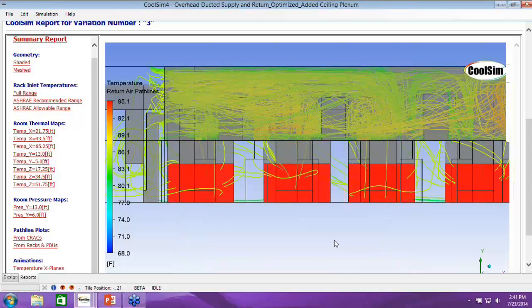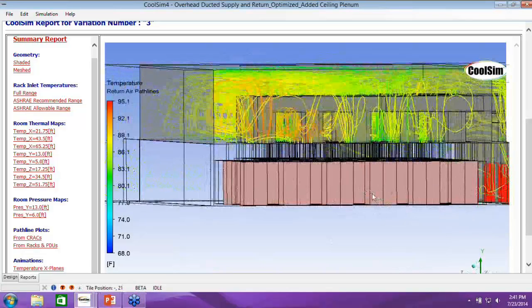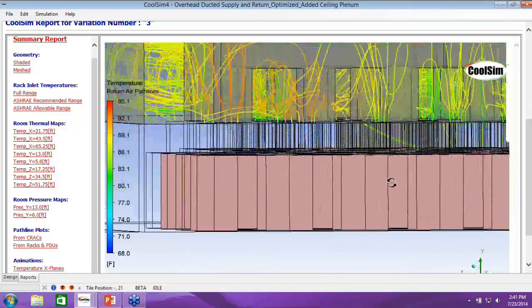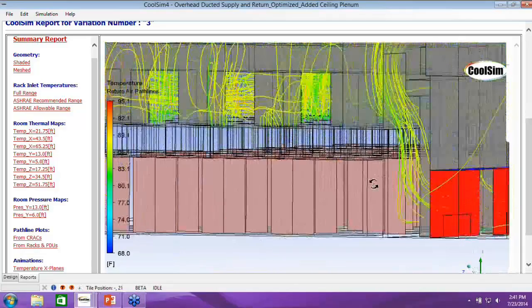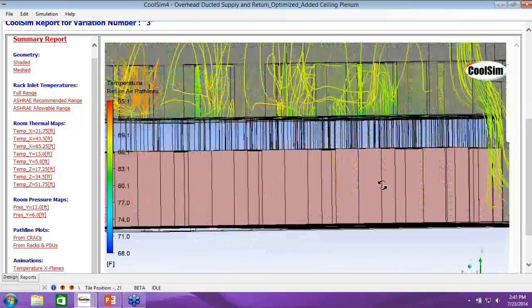It's a mixing issue, right, Magnus? No, exactly. That's what we said before, that the goal with air management is to avoid mixing. And by installing this drop sealing, you actually did that. It's an enclosure technology. You separated the cool air completely from the return hot air.